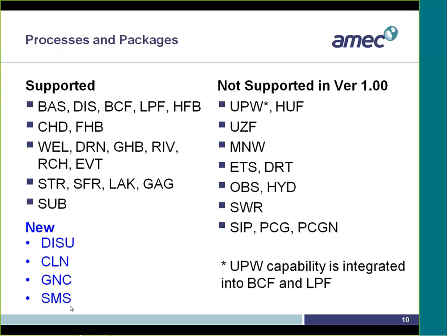And both solvers have different solution schemes. They have symmetric solution schemes, PCG, preconditioned conjugate gradient methods for symmetric matrices, and they also have unsymmetric schemes like orthomin and BiCGSTAB, for unsymmetric matrices which come out of this upstream formulation and the use of Newton-Raphson linearization.